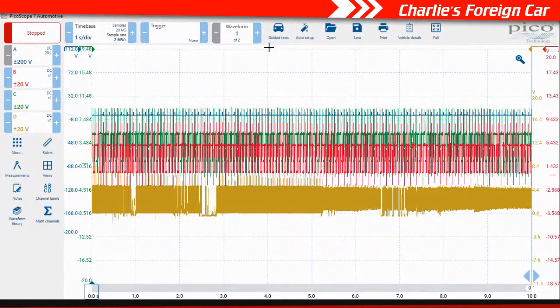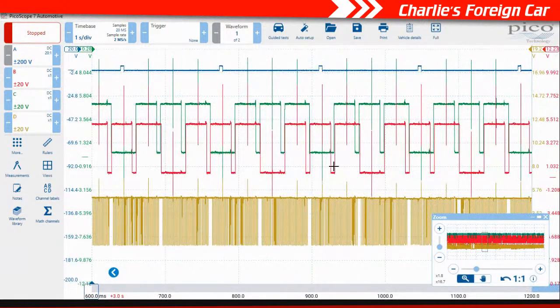So on the screen back here, on our first waveform screen, something happened with our crank signal right over here. Yeah, that's what I was looking at. Kind of funky. I think maybe we have a bad connection. So I'll make sure that we grab our zoom shot in the nice spot of it. So we'll zoom this right here. And now we're looking at the green signal, right?